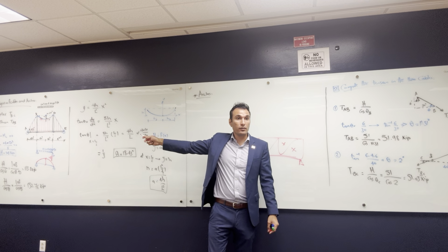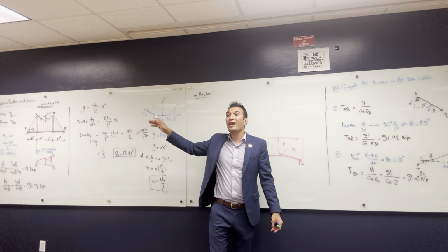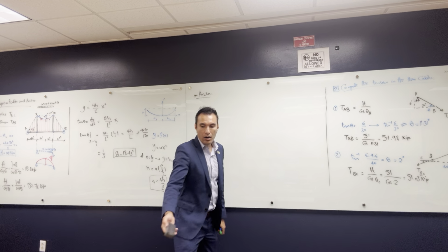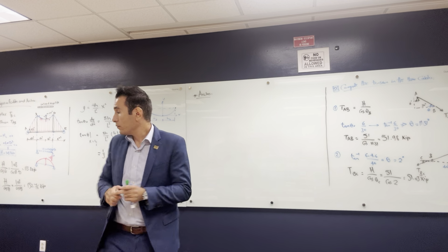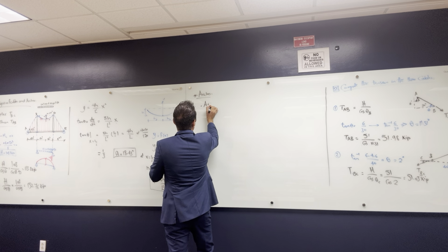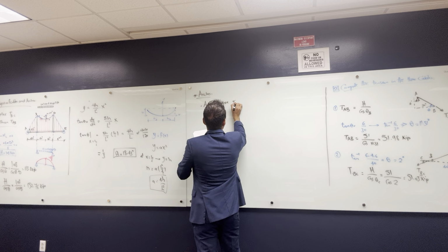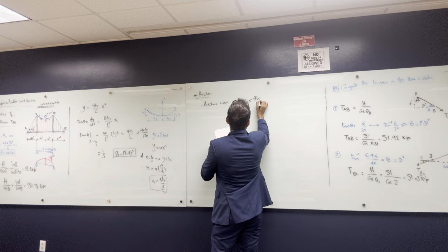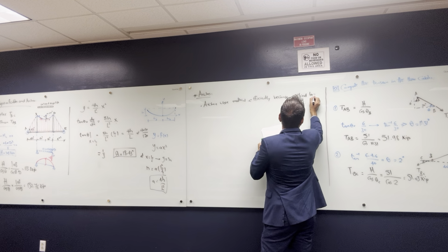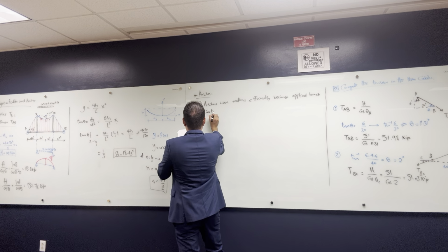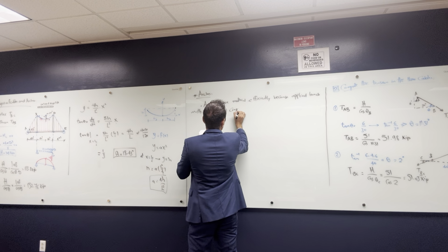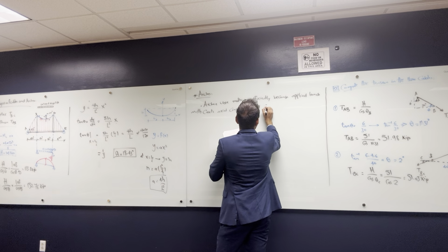What other system? This one, the cable system. It only takes tension, but it's not like a truss, it doesn't take compression, okay? And has all moment equals 0. Also arches, somehow arches can have 0 bending moment. Arch systems, let me write this. Arches use material efficiently because applied loads create axial, or let's say mostly axial compression on all cross sections.